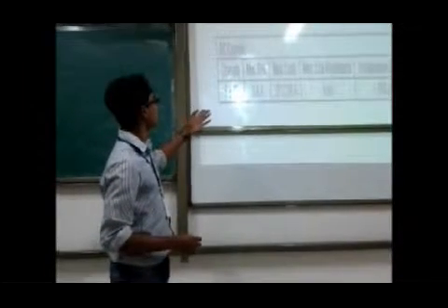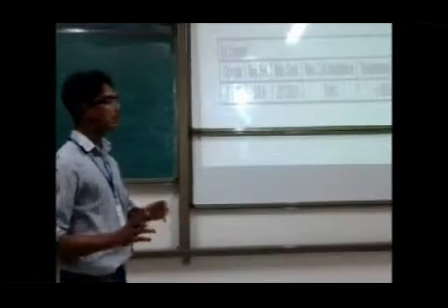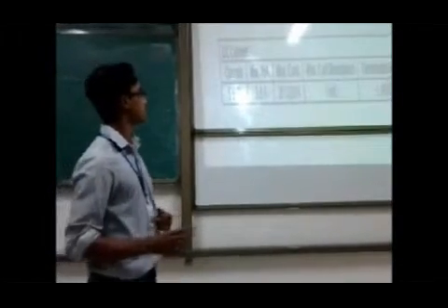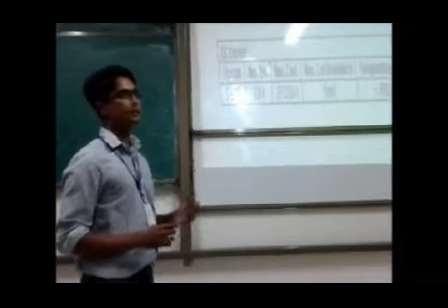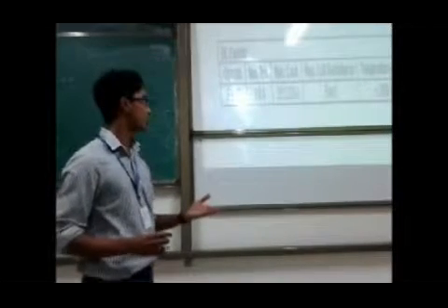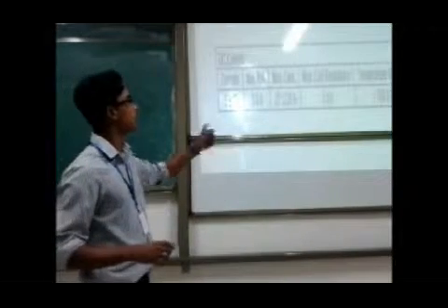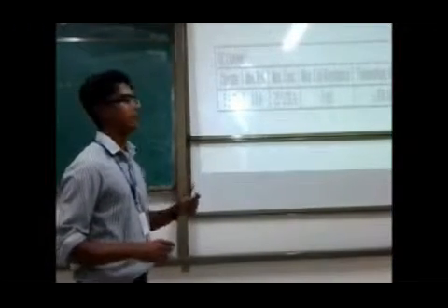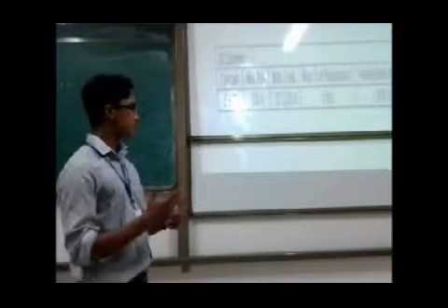And these are the specifications. It should be operated within a range of 5 to 25. The maximum continuous current, that is the maximum current which can be used for this sensor in any application, should be around 20 ampere. Maximum coil resistance is used for measuring the voltage drop across the coils and also the power dissipated. It should be around 5 milliohm. The temperature stability gives the variation of operate and release points, how much they vary according to temperature.